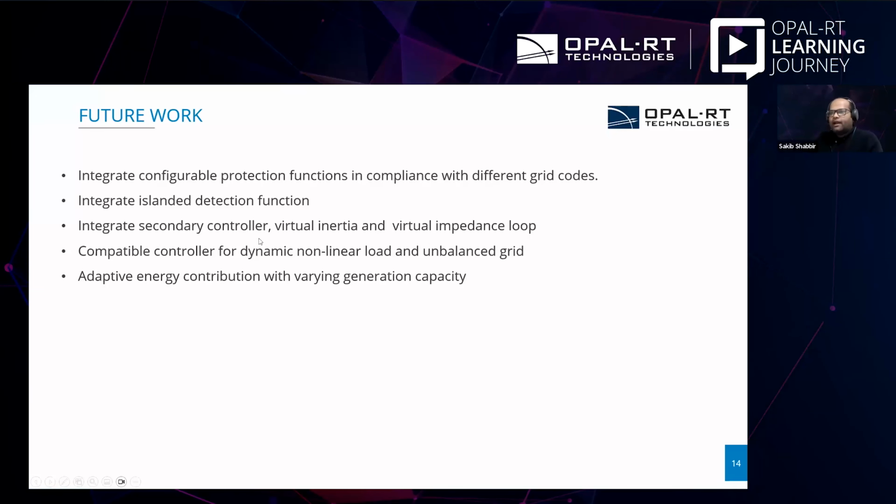With the current version of the smart inverter library, we do not have any islanded detection function, but that is available with the grid following library, so we will integrate that function in future. We can also integrate different configurable protection functions in compliance with different grids and standards. So these are the things that will be added in future releases of the smart inverter library.